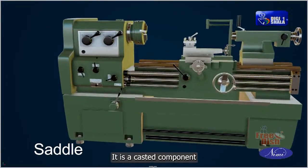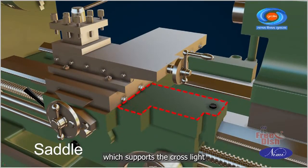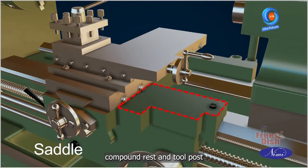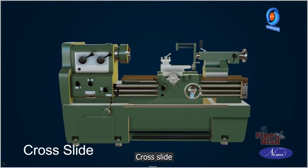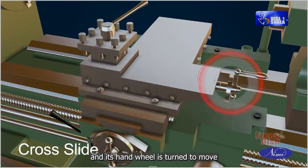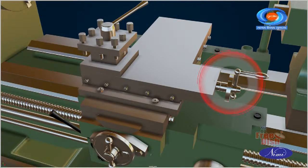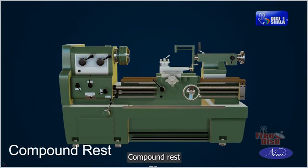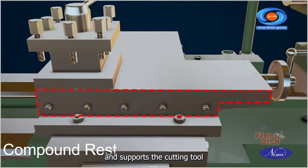Saddle. It is a cast component positioned on top of the carriage which supports the cross slide, compound rest and tool post. Cross slide. It is positioned on top of a saddle and its hand wheel is turned to move the cross slide perpendicularly to the axis of the lathe. Compound rest. It joins the cross slide with a tongue and groove joint and supports the cutting tool and tool post.